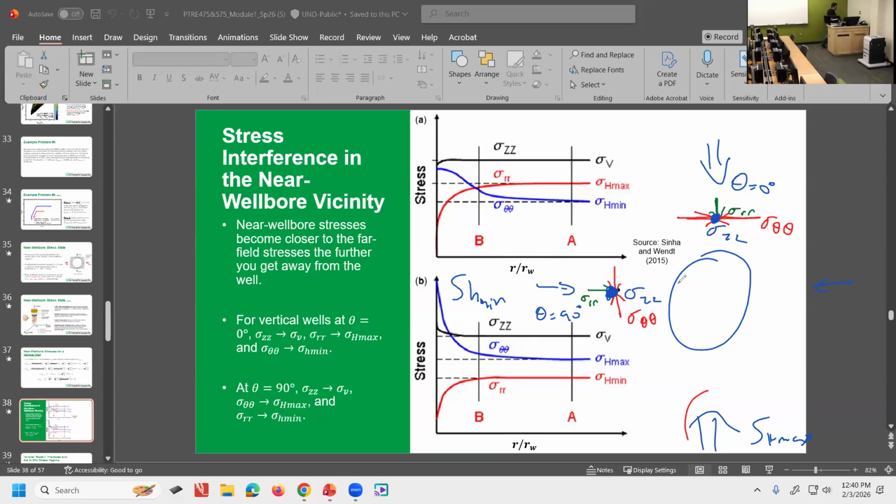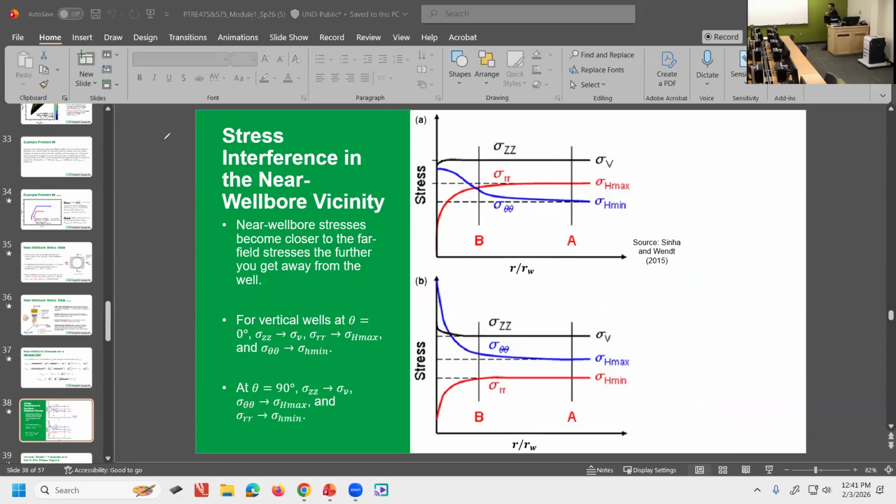would be sigma XX. When I was a PhD student, I was setting my wells parallel to the Y-axis. So the axial stress was called sigma YY. It's the same thing. I think in geomechanics, you saw some exercises that were sigma II. Same thing. Whatever you call that axis to be in cylindrical coordinates. Remember, in cylindrical coordinates, you have only one linear axis, and generally it's called Z.